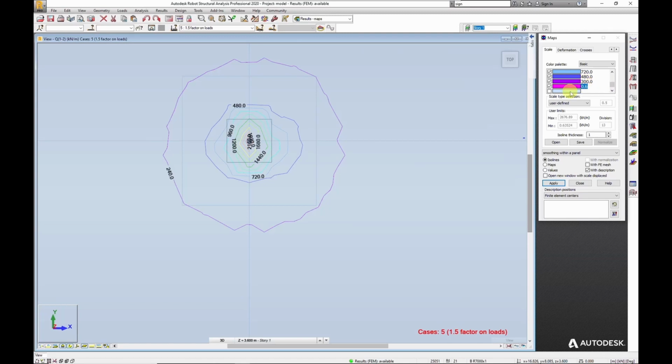So again, that's my resistance. If I choose apply, we can see this contour of 300 kilonewtons per metre is what my resistance of the concrete alone is before we have shear reinforcement, and we're testing it against the control perimeter.